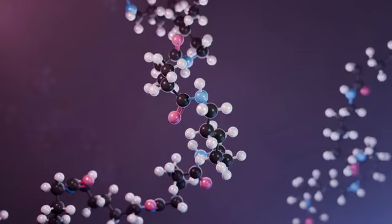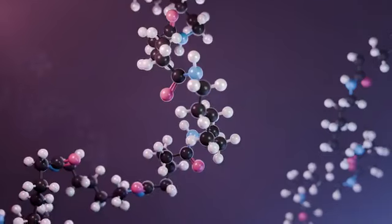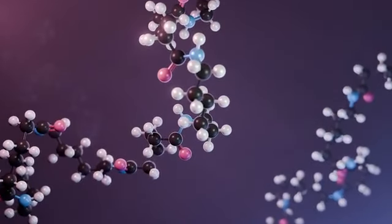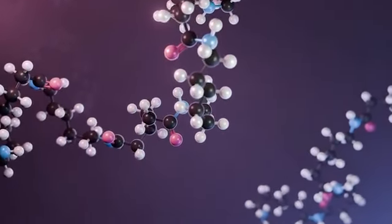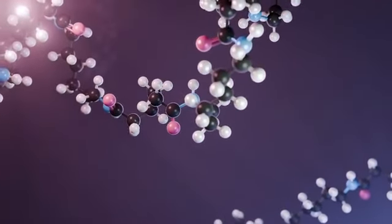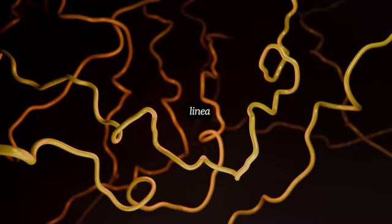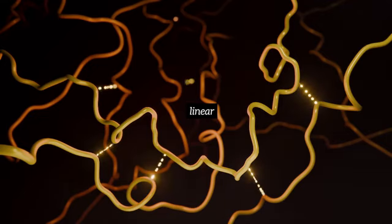Polymers usually have a dominant structure type, depending on the polymerization conditions and the monomer involved. This affects how the polymer chains interact with each other, and plays a key role in determining the polymer's properties. In a linear arrangement, the polymer chains are continuous lines, with each mer in the chain only being connected to two other mers. The chains are held together by relatively weak intermolecular forces.